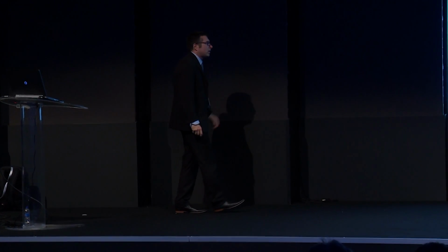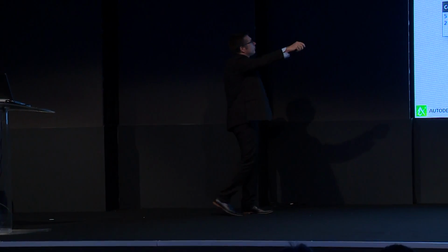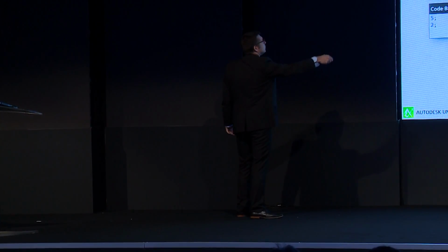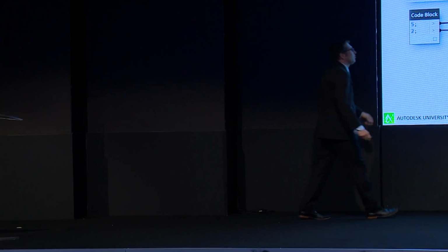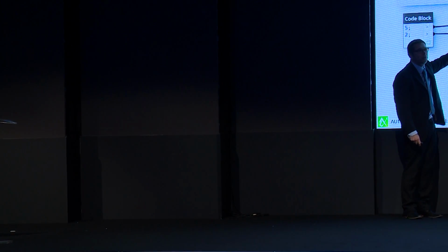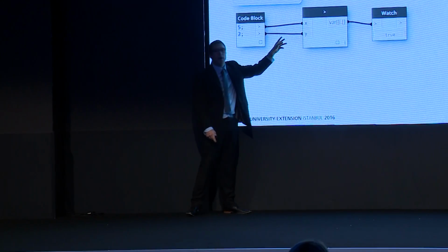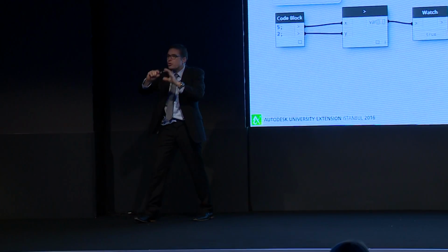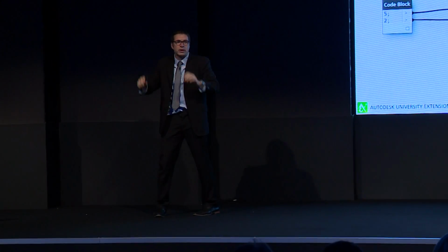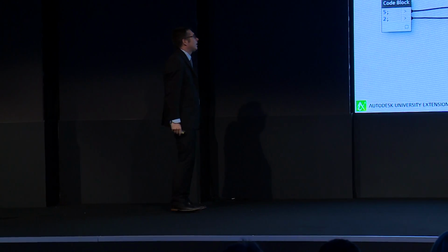Dynamo, that's it. You've got some nodes here with inputs and outputs. You connect nodes by wires, and by creating this kind of diagram, you can accomplish a lot of things in Dynamo.